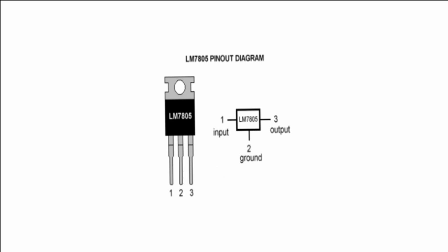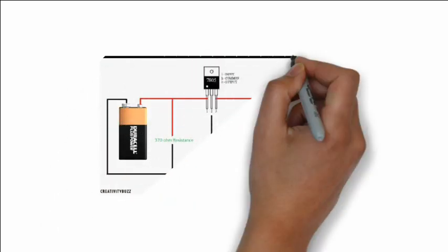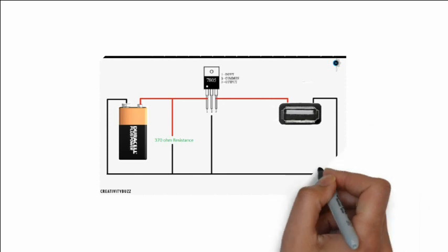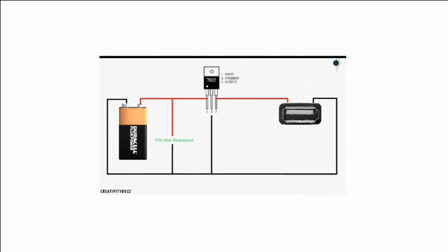Okay, now the time to practically do something. So guys, ready? Okay, let us see how IC7805 really works. So basically we will design and craft a simple cell phone power bank just to see how it works. Okay, the power bank will be working with basic Android phones and almost all feature phones. However, it is advised not to use it as a primary charging source. We'll be witnessing how we will regulate a 9 volt input voltage to 5 volt output voltage for our concerned usability.